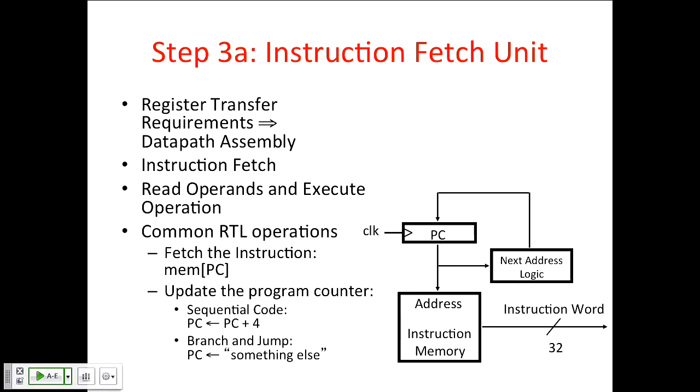We have the instruction memory here. Notice the PC just feeds in as the address to this memory, and the instruction word comes out. This is just combinational flow-through. So the PC changes at the clock edge, the outputs of the PC change and go to the instruction memory, and sometime later the output will change to hold the correct instruction bits.